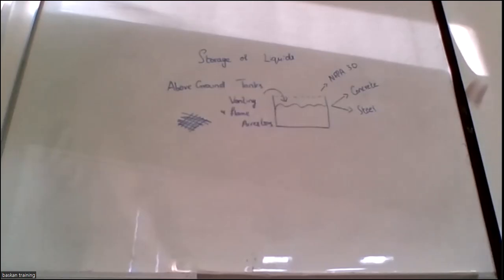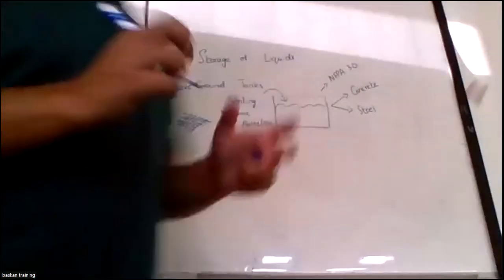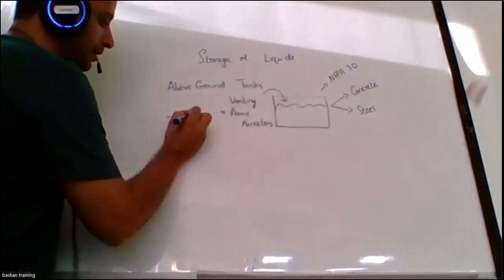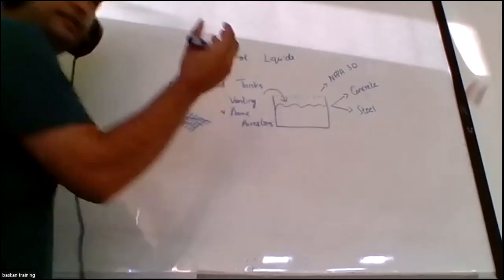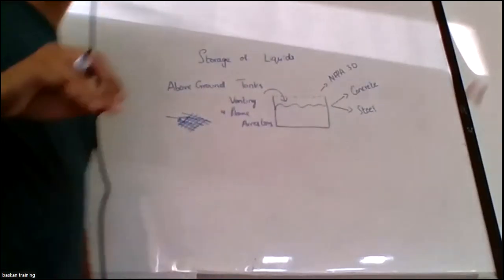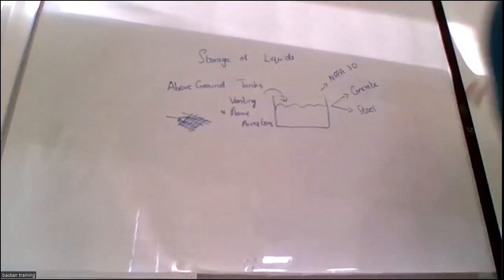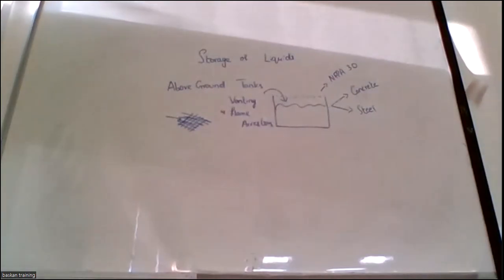On major big tanks you will see permanently fixed fencing. The purpose is that whenever a flame appears, the fencing absorbs the heat and distributes it over the fencing. So what will happen when you remove heat from a flame?